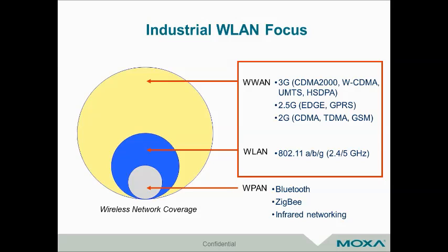There are many different types of wireless technologies that are available on the market today. Not all of them are going to be appropriate for industrial use, but some of the ones that you may see out there are things like Bluetooth, Zigbee, 900 megahertz, Wi-Fi, and cellular, as well as WirelessHART, ISA100, and some of the other various smaller standards.